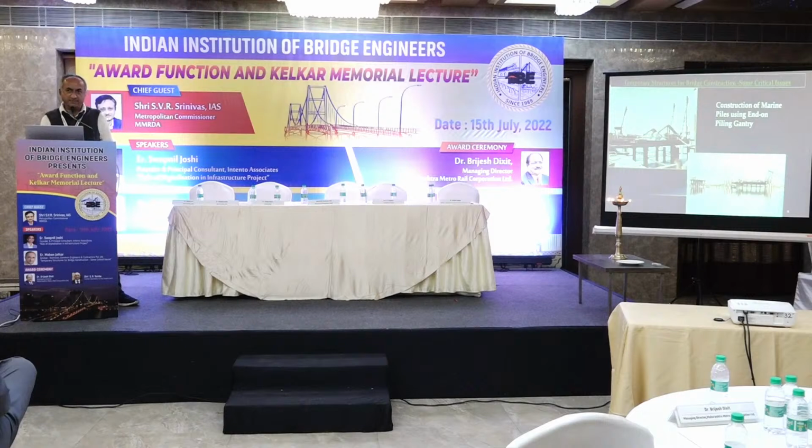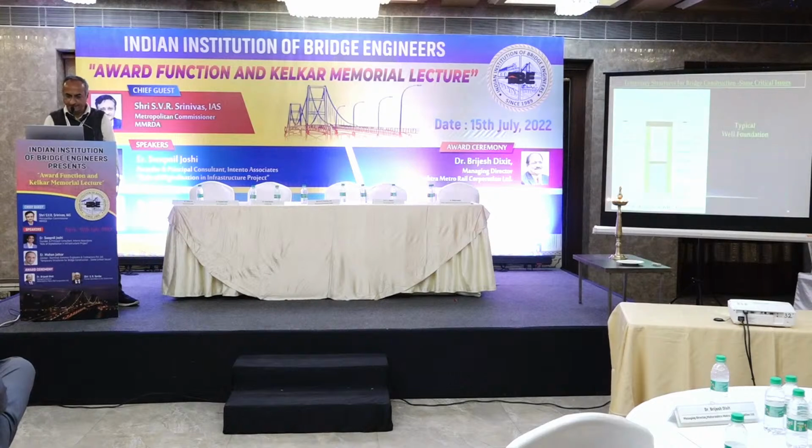Piles, whatever I am mentioning is the temporary structure associated with that particular type of construction. So here you can see an end-on piling gantry, which is mainly used for marine piling. It can progress on the already constructed piles or temporary piles, and the piling rigs, etc., are mounted on that platform, which is moving ahead.